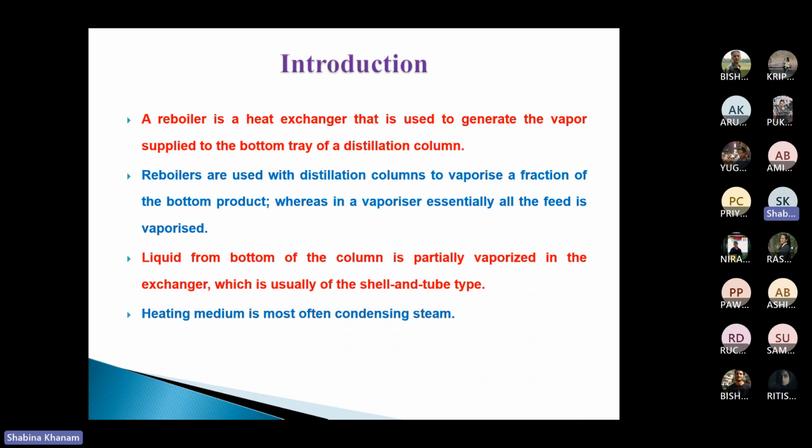So what is the point to consider here? When the feed enters as a liquid at boiling point, whenever it takes heat, vapor formation starts immediately, right? So on both sides, shell side or tube side, whichever you are considering, we have phase change. If sensible heat is there, it will be very little.